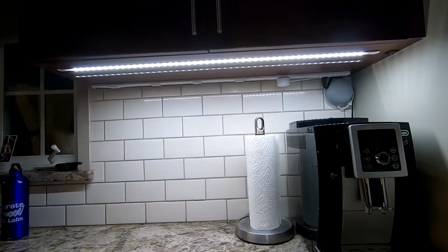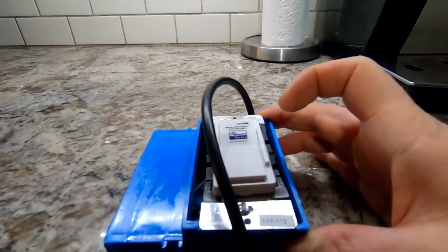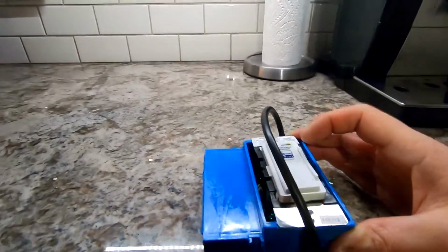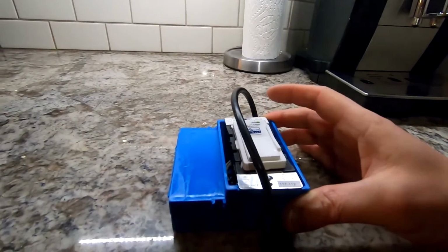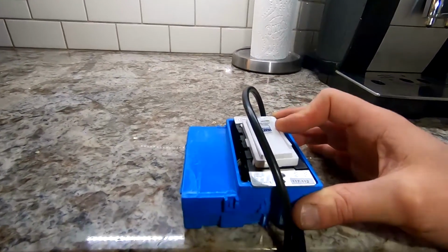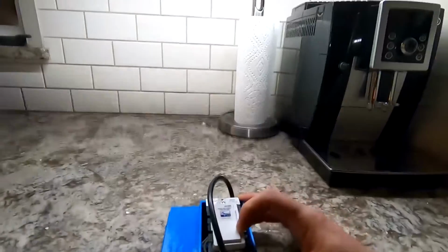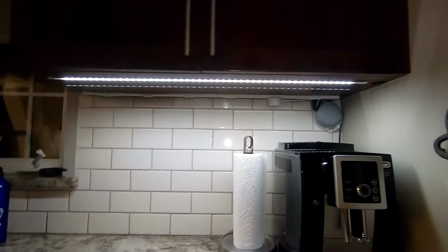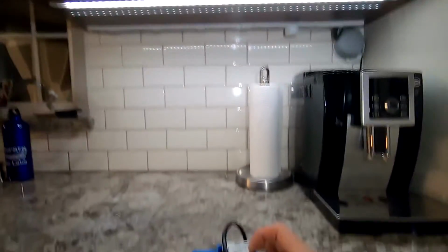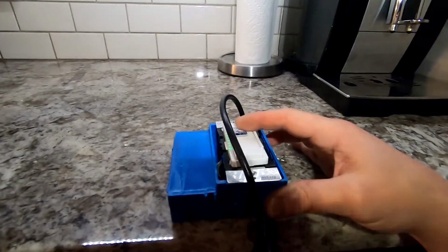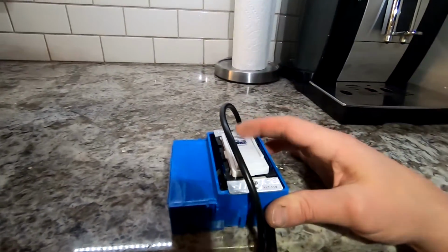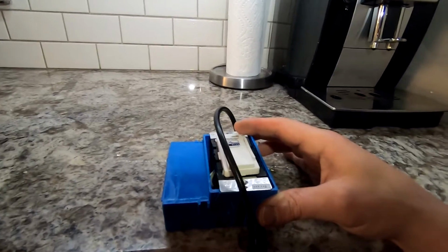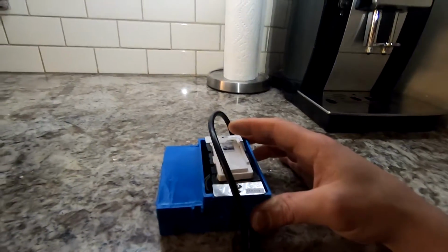So up and down. So we know by testing this dimmer manually, dimming the cabinet lights, that we're good. So when we connect this all to the software, and to Google, and to the apps, the verbal commands will work just like you saw with my hi-hats in the kitchen. There's no flicker. You can also set this dimmer in the settings through click commands that this is an LED load, which I haven't done yet. I'll do that off camera.